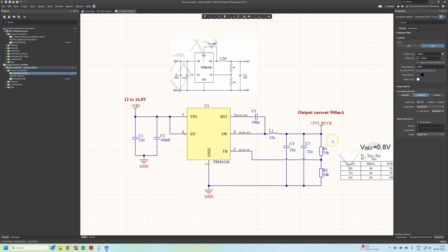So you might have more ripple current and a less stable output voltage. That's why you have to select your specification, whether you need a fixed voltage and what output current you need, and then make your calculation based on that. I have already provided a document, which I will put in the link, where you learn how to make all this calculation for this specific case.